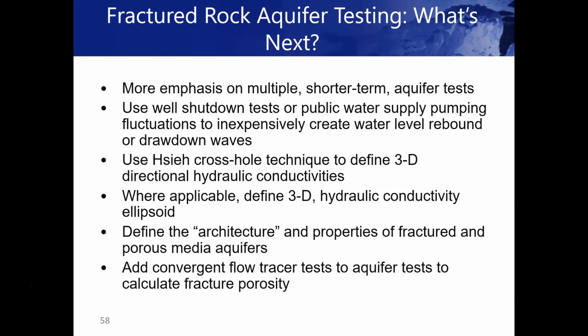So that's a complication in fractured rock wells. If you pump it way down, you're going to dewater a lot of the water-bearing fractures. So they'll first become not a function of water level any longer, and eventually may dry out. So that's a significant issue to deal with. I could try to give you a longer answer to that, but it would take quite a while. It's just something you have to deal with.